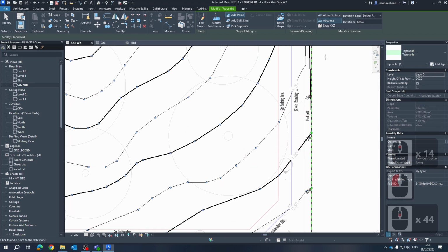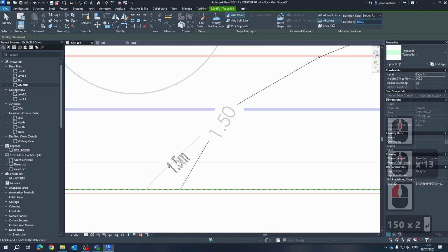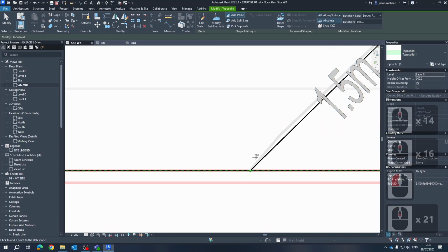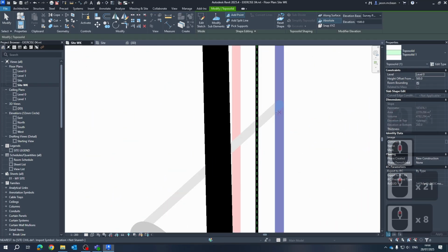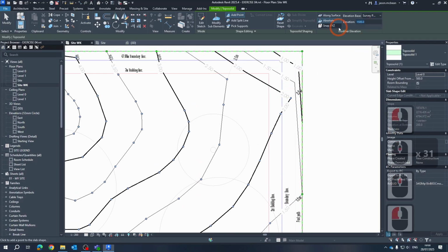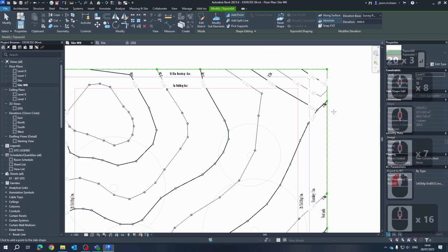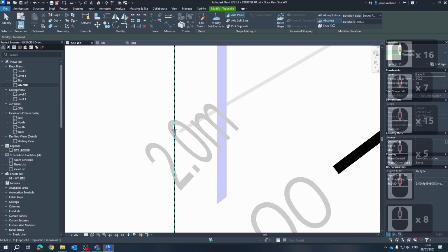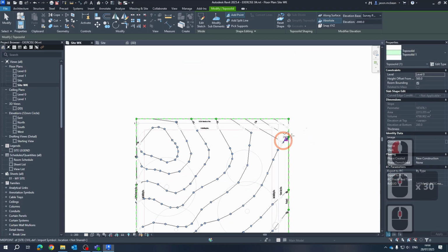It's a little quirk that I've realized that's in Revit, in this new version. I need to make this 1500 now, and that point I'm just going to put somewhere on this line over here. It has to be on this boundary, good, and I'm just going to go to this side and make sure that I fix this one as well. So remember 1500, so anywhere is fine for now. Okay, then I want 2 meters, 2000. So that 2000 mark is going to go over there, and make sure this 2000 over here, so that should go over here. Good, so we fixed that one, 2 meters.